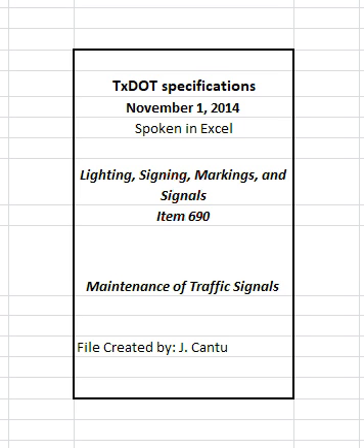Label each cable brought into the controller cabinet. Coil 5 feet of cable neatly on the traffic signal controller cabinet floor for each cable. Install solderless pressure connectors that meet the requirements of the NEC for all wires attached to terminal posts. Use a ratchet-type full-circle crimper for insulated terminals to provide a solderless pressure connector.